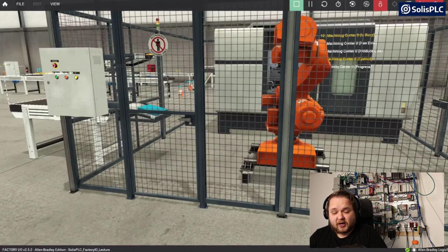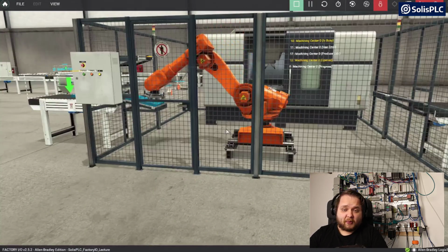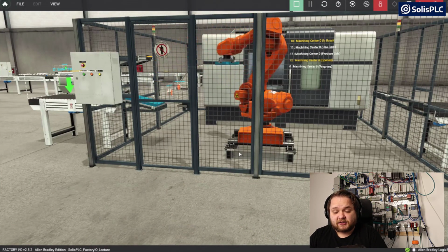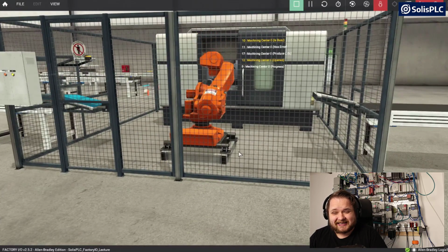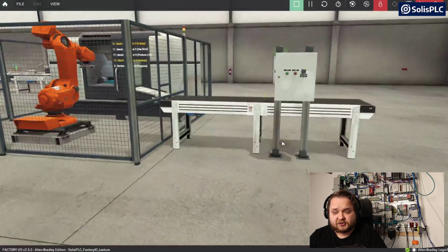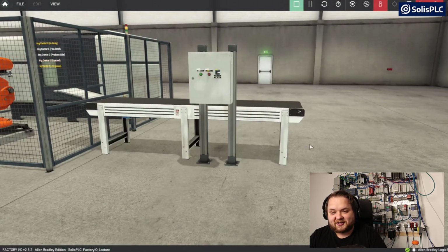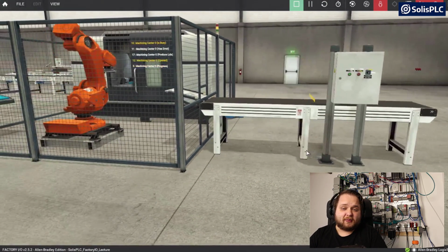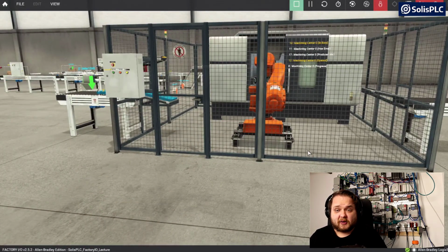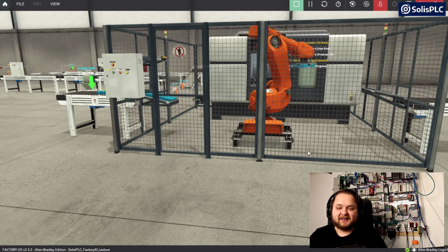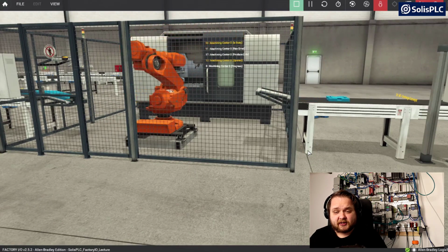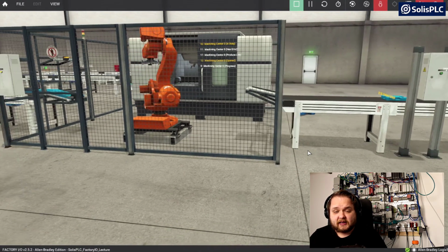It looks like we have raw materials coming in. It looks like the robot is going to automatically pick up that plate without me having to press the start push button. It should process it inside of the CNC. It should then place that on the discharge conveyor, which is going to bring the finished product onto the floor. But the robot should repeat the sequence without me having to press that start push button, or without having an operator that presses it. So in other words, we are continuously creating one product at a time.